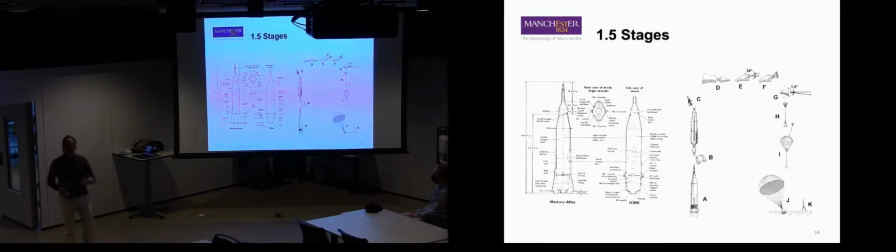That's not the case for things like Delta or Atlas V or Titan. They use what are called isogrid structures, so they actually chem mill or machine extra stiffeners into the side, and it looks kind of like a diamond shape. That strengthens their rockets.